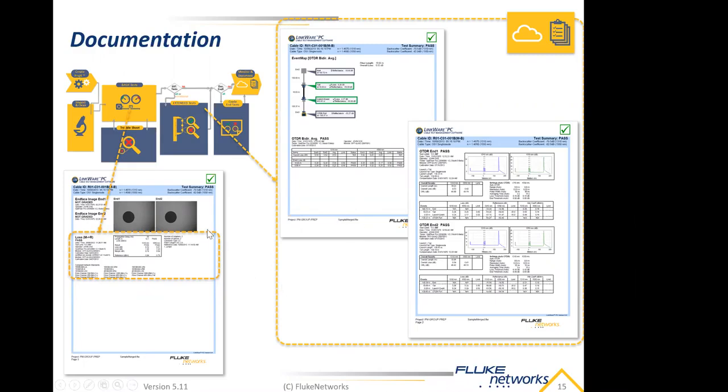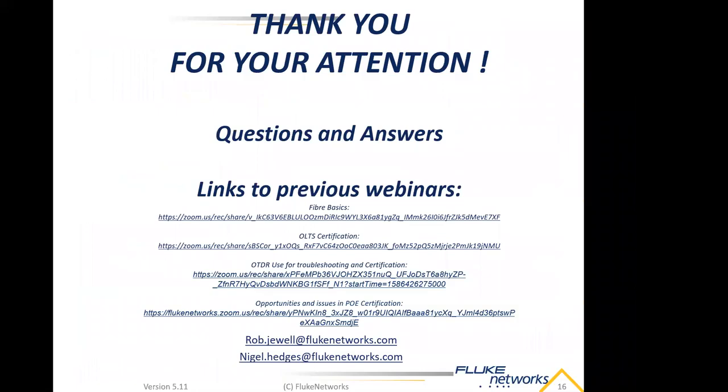More importantly, perhaps, also included are the end face images. Now, the end face images are time-stamped, so they should indicate that the end face images are those taken as you leave site, not as you arrive on site. So the client should be able to very clearly understand that when you finished the testing and covered the installation up, the end faces were clean and undamaged. That's the important thing.